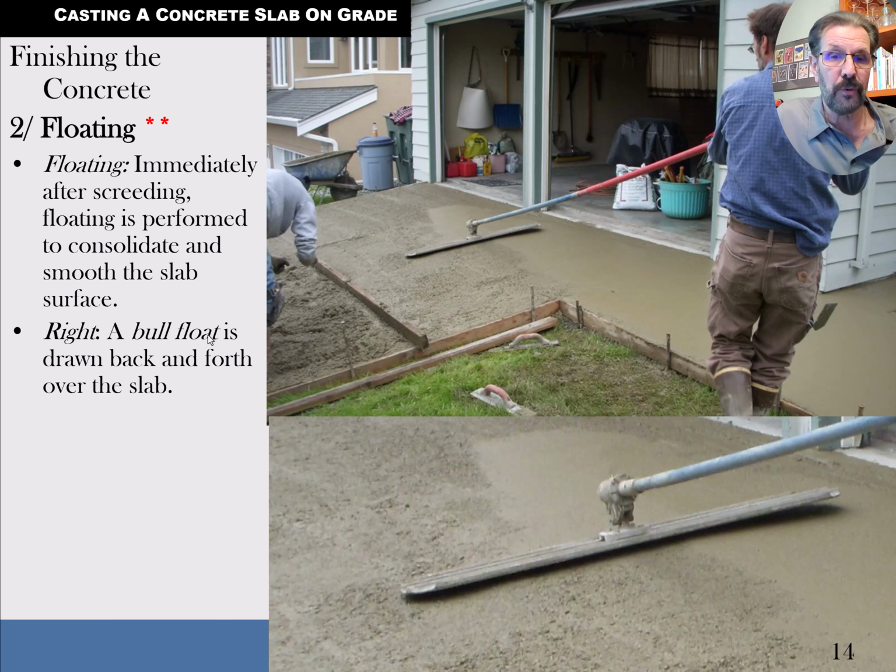What you never use, for troweling or floating or for screed or any other concrete tool, is anything made of aluminum. Aluminum violently reacts with concrete, so any little specks of aluminum that wear off into the mix can cause a pocket of expansion. And so, we do add aluminum very, very carefully into a mix, very evenly distributed, but you don't want a chunk of aluminum coming off as it's wearing while you're going back and forth with any kind of a tool.